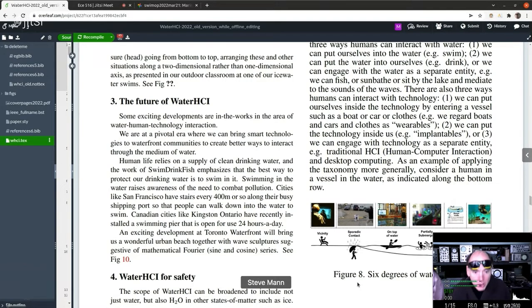What I was saying is that head and flow are separate concepts, kind of like the Thevenin and Norton equivalents of electrical engineering. You can have a great big pipe at very low pressure, and if you open that up and it sprays on you, you don't really feel much. Or you might have a small pipe at really high pressure.